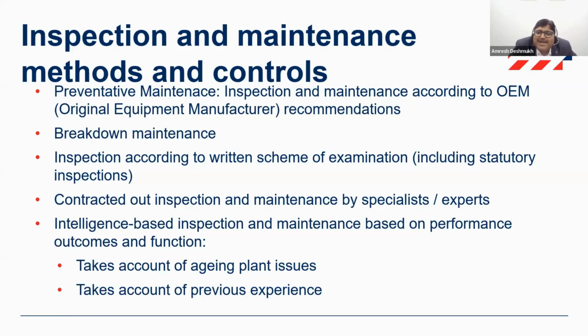And definitely ensure that you have a fixed predefined cutoff time as well. Don't use it too far, because if you look at the bathtub curve, beyond a particular point in time of the age, you'll find that all those equipments which were bought together would start failing together. So it's necessary that you have a predefined cutoff for each of your critical assets.